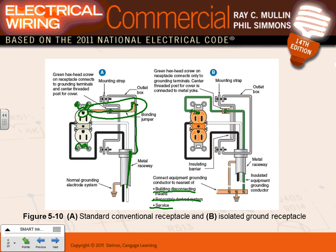Now this is not how they do it, but this is one way of doing it. Does that make sense where this wire is going? Can I emphasize that if you have an isolated ground receptacle, then Andrew, my friend, you have to have two grounds. Do you guys understand that you have to have two grounds here?